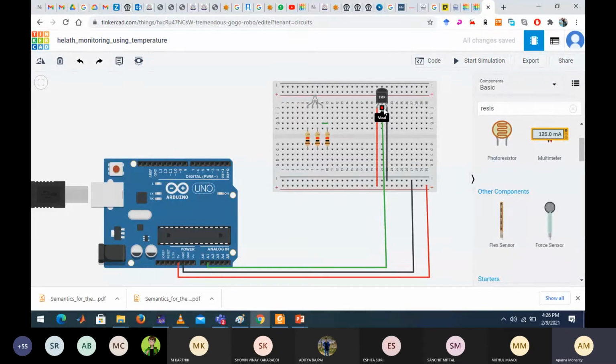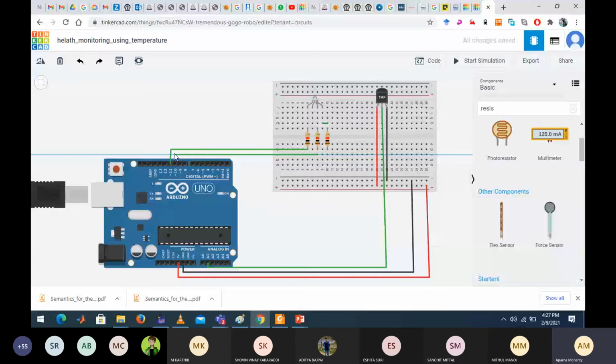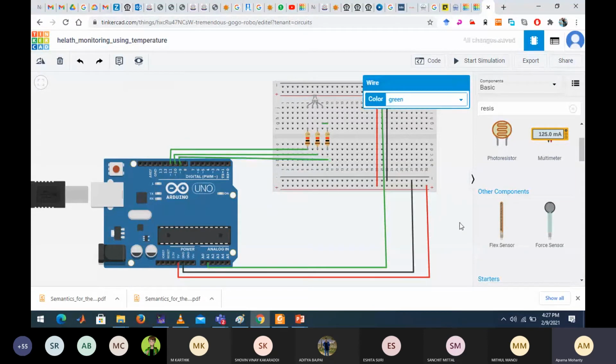Next we need to make a connection to the LED, through the LED and these resistances. So how do we go about that? See, the resistance is connected here. We will make connections to 3 different pins. We will be using the 11th pin here, then at this terminal I can use one more pin, the 10th pin, and here suppose the ninth pin I can connect. Could you connect this much, everybody?